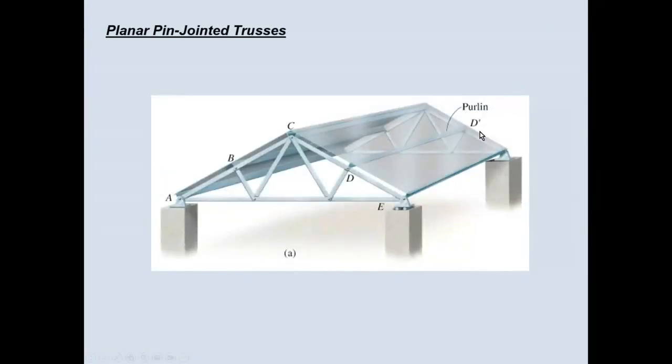So this is three-dimensional. For the sake of simplicity, what happens in the back plate is the same as the front plate. All right. So we assume that both of them are the same. But look at the roof structure. The roof structure only connects here, and then there's a gap. Everywhere else there is a gap. The roof is only allowed to sit at these pins. So the roof is not allowed to push against the bar in the middle. It can only push not directly to the bar, but to the pin.